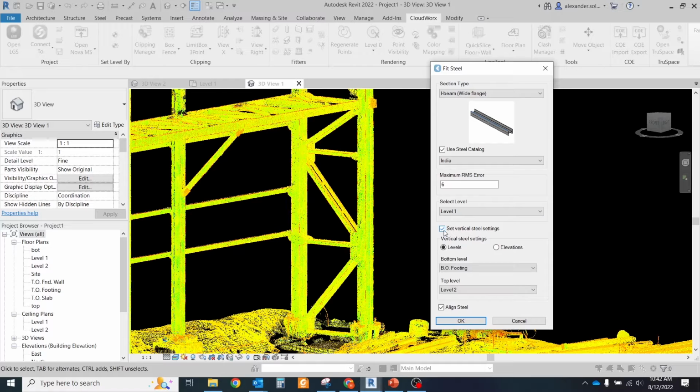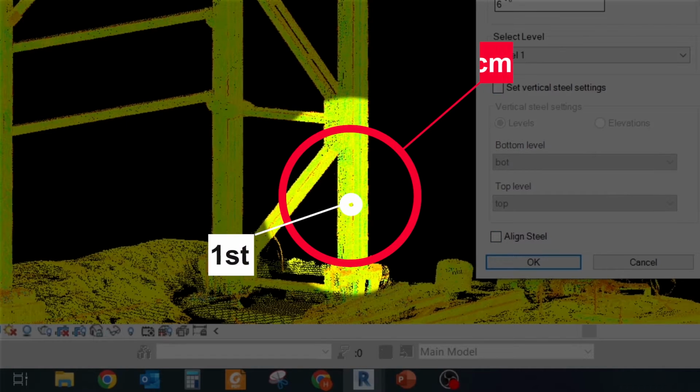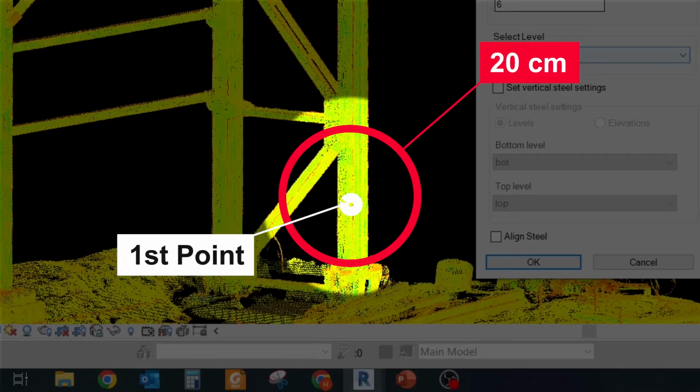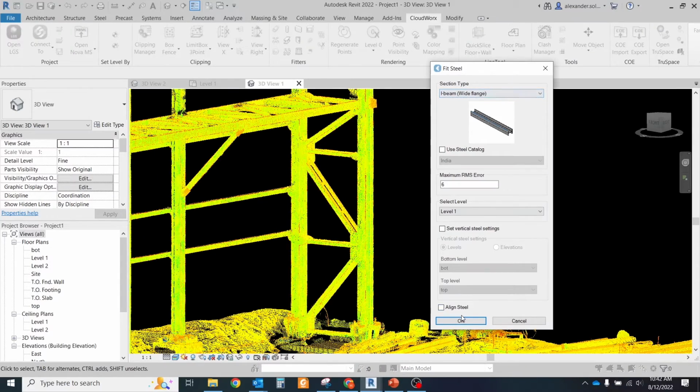The first, primary selection point, is on the part of the structure that adequately represents the structure's cross-section. That is as good and as clean as possible with respect to overall structure. The area, about 20 centimeters along the primary axis around the first primary selection point, must be free of attachments, and adjacent structures must have a distance of at least half the target structure's cross-section extent.